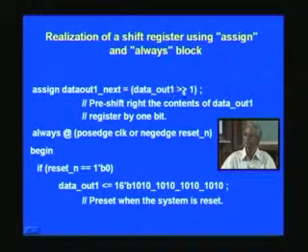This is the symbol for shift, right shift as such, as we had seen earlier. And if you want left shift, you have the arrows the other way. And we assign this to what is called next. We have the same name, and this implies next value is going to be this, and this value will be used within the always block when the clock really makes its appearance. That's at the positive edge of the clock.